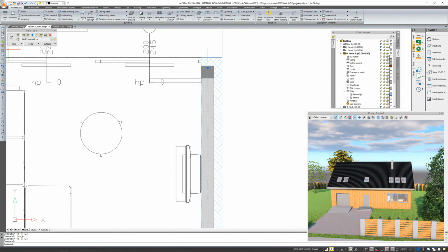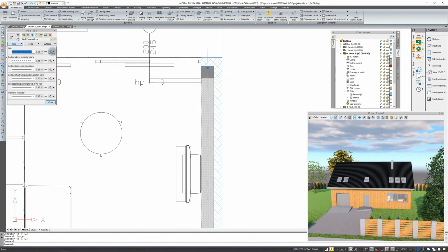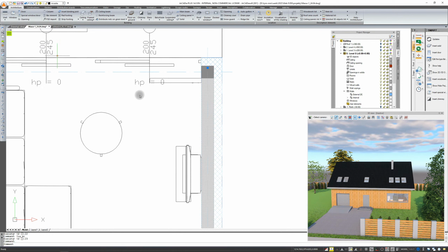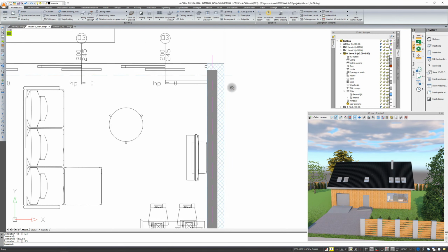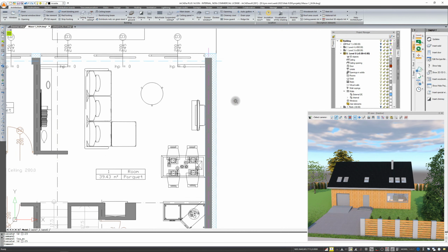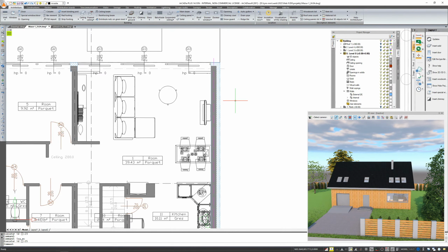The moment you define in the wall that, for example, a pen is of a different color than on the view, here, for example, I will make it pink, then the colors that we assign to a given wall will no longer be taken into account. Only those elements that have not been changed will be colored here. So at this point, the line from the axis that I have just modified manually will not be changed together with the color for the group.